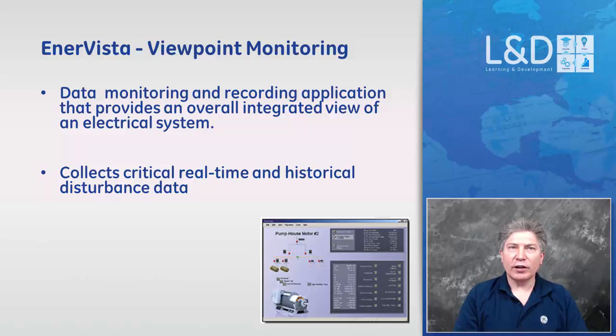So we not only collect real-time data, we also collect waveforms and sequence of event recorder data. We can control and monitor the status of switches and breakers. We can set up an annunciator panel to notify the operator that an abnormal condition has occurred and send the status to 5 email addresses. There's a data logger with a 1-second resolution built into it. And it also records its own system events in the event that something goes wrong within the system itself.